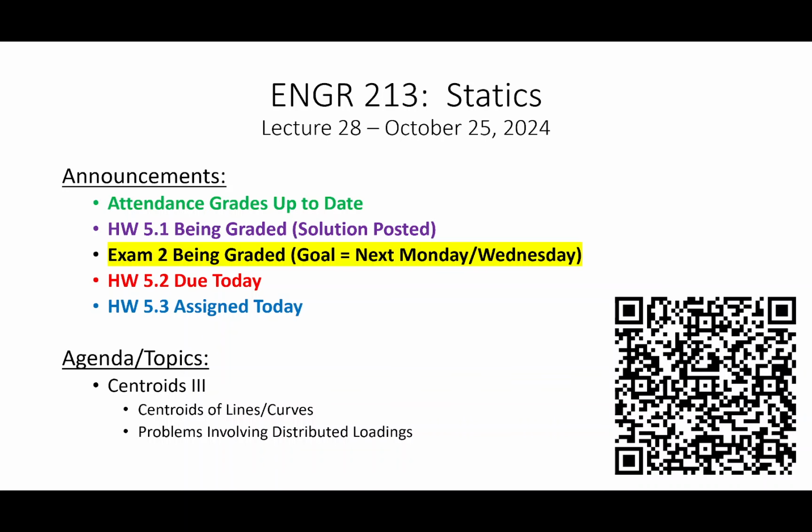Maybe I'll put a hole in it right here and a hole in that face. How do I compute the location of the centroid? Well, same idea. Break it up into simpler components or simpler regions. So maybe I have a rectangle, a triangular prism, a cylinder, and what have you. So again, a lot of the same ideas, okay?